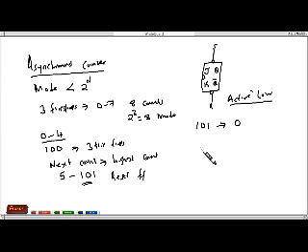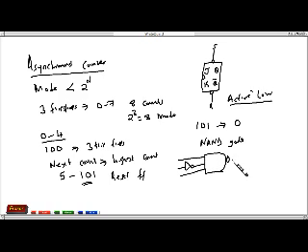So in that case, we can use a NAND gate. We pass the outputs of the flip-flop to the NAND gate like this. So if this is our NAND gate, we pass the 3 inputs, but the middle one we first invert. That's the last one. Then this is the output of our flip-flop.